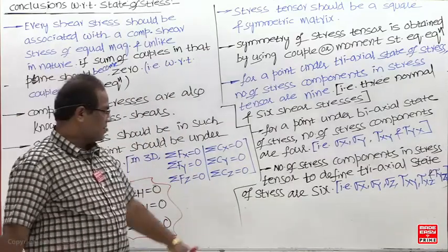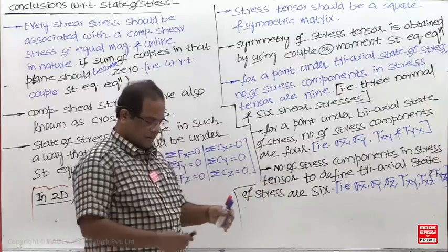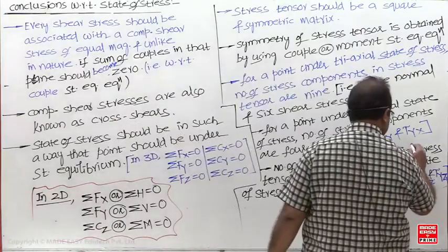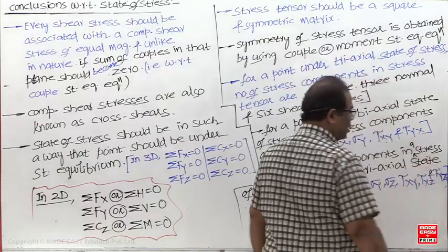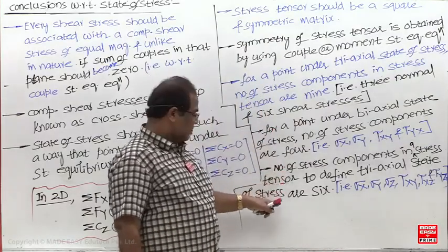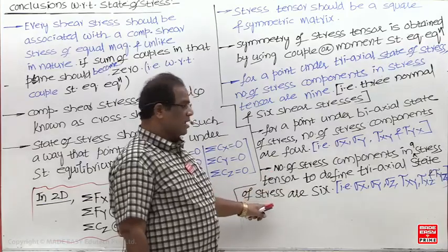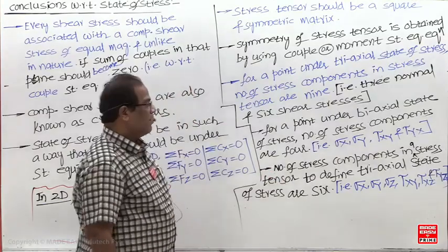Now same thing for biaxial, write down now. Number of stress components in a stress tensor. By default we ask what the total you have, but if define is mentioned, you have to go for independent components: 6. But same thing for biaxial, you have to go for 3: sigma x, sigma y and tau xy.